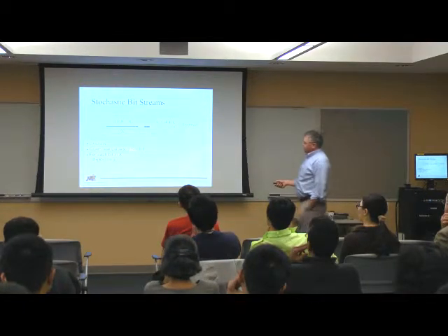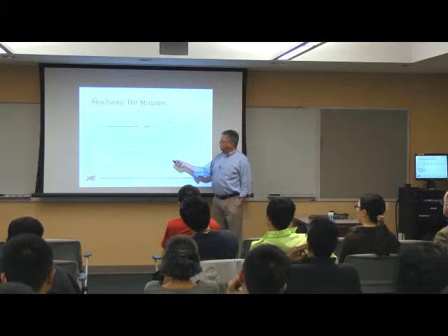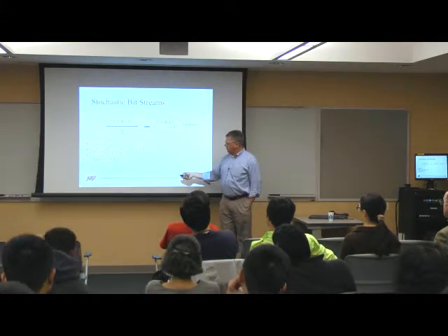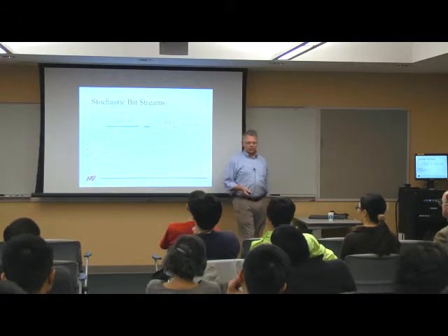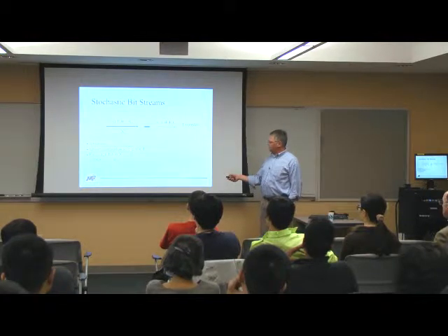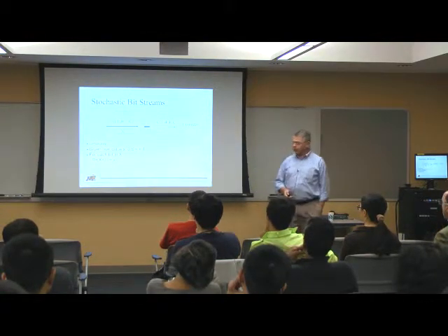So mathematically, what I'm really thinking of is that for each one of these bits, the probability of that bit at any given time being a 1 is x, where x is the value that I'm trying to represent. And that gives me real values between 0 and 1 that I can encode using this format. We call that a unipolar format.